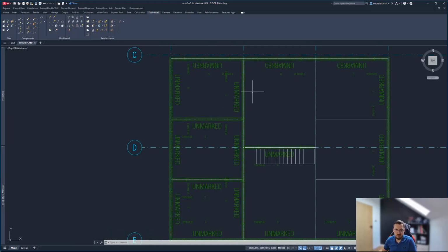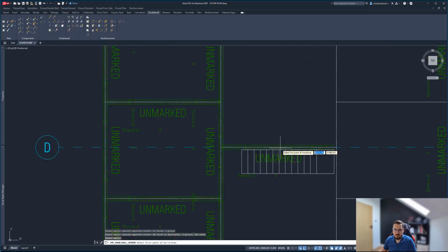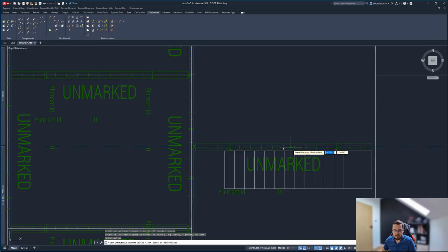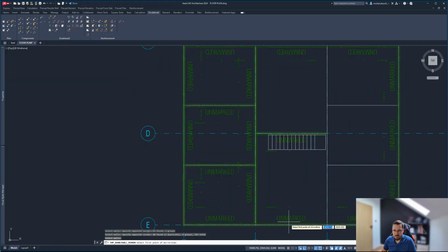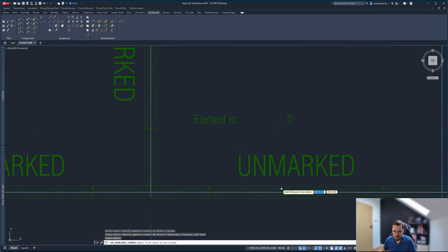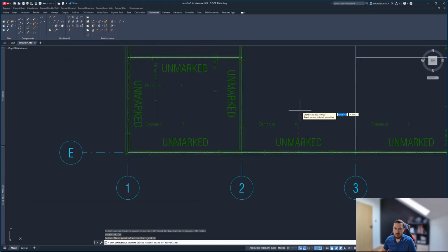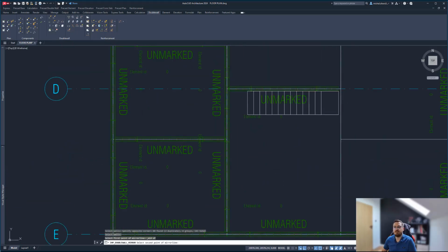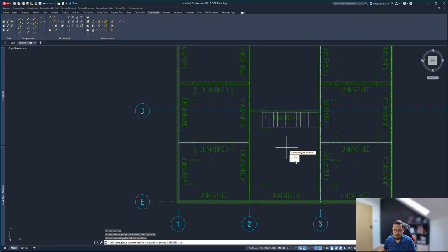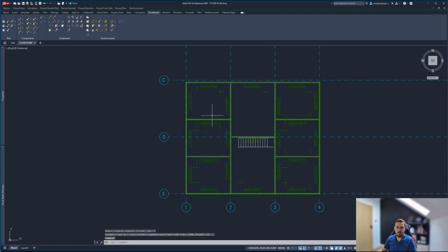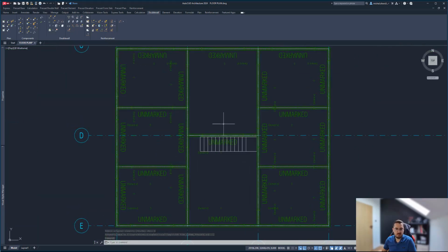With that quickness, I'd like to follow up with being able to mirror some walls. So I'm going to do that. Click, click, like that. My walls are now marked for mirroring. I'll just need to find the midpoint of my line here. Select that, and walls are done. Basically, my double walls are now done. My stairs are nicely aligned, and that's all good.